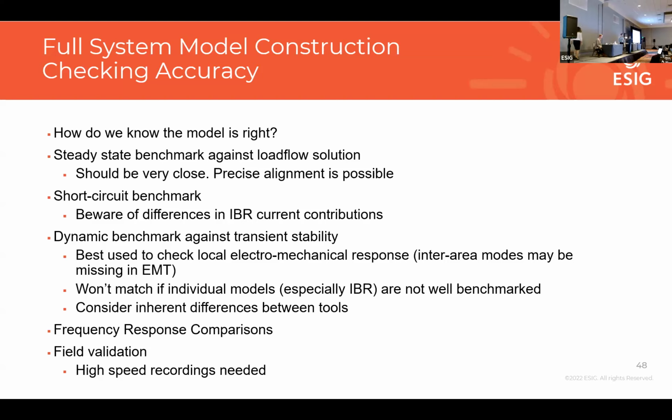Okay, very briefly, how do we know the model is right? How do we do some verification on it? Of course, we can look at the power flow inside of our model, especially the initial power flow, and compare it to what we would have inside of your load flow program. We can get this power flow to line up very closely if we're very careful with our initialization. We can look at short circuit currents. If you have short circuit levels that you're expecting based on your protection software, or maybe even your phasor domain simulation for a three-phase fault, then you could compare that fault current to what you get in your EMT simulation, if you apply the same fault and measure the fault current.